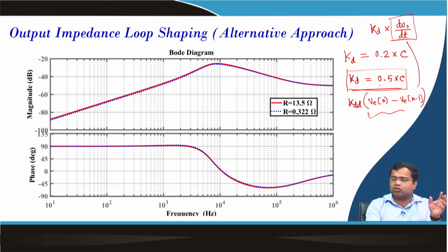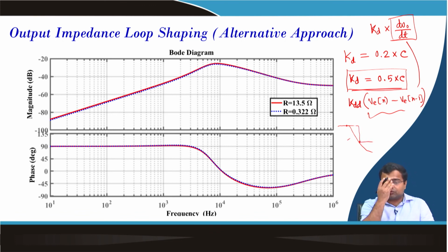That is why we may not opt for a very large value of Kd, which may create some delayed effect, because if the actual voltage is deviating and you take samples here and here, you will not get the actual derivative action, since you are losing the information in between. So, we are keeping a conservative choice of 0.2.